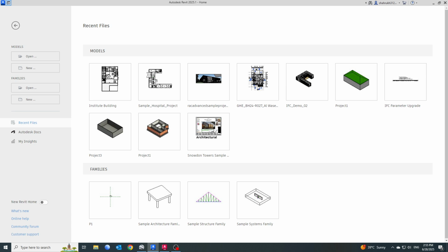It already has the coordinates. Once we attach these coordinates to Revit and properly georeference it, and then start working on it, your model will be perfectly aligned with the coordinates. Whenever you export it to IFC or to any other CAD form or any other 3D format with a proper geo coordinate system, it will be properly georeferenced.